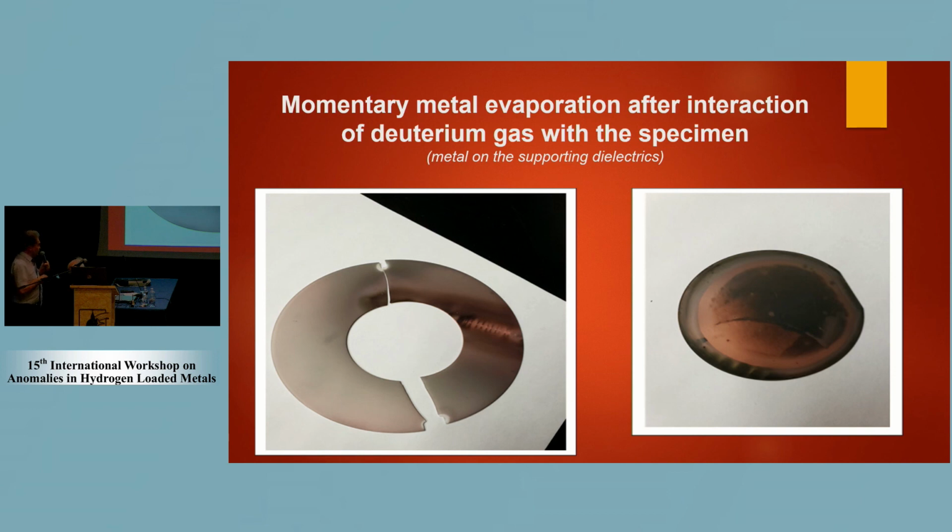Which means that indeed momentary evaporation of the constantan wire has occurred. I don't know exactly the time, but indeed it was momentary evaporation, because getting this clear picture of the specimen, unusual as it is, shows that despite significant vibrations in the system, the clear picture takes place, which means that the time for evaporation is less than 1 second.